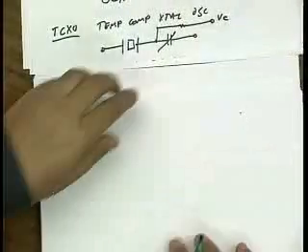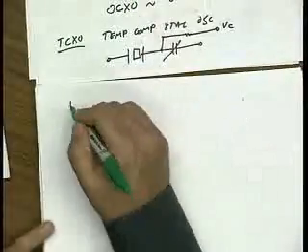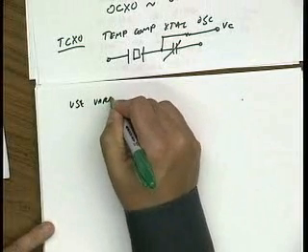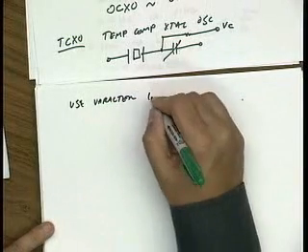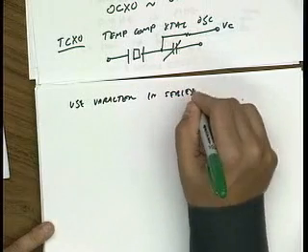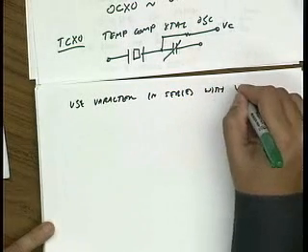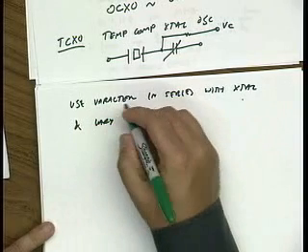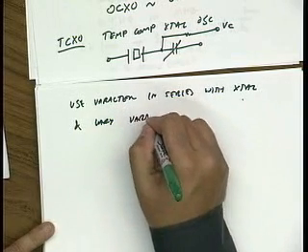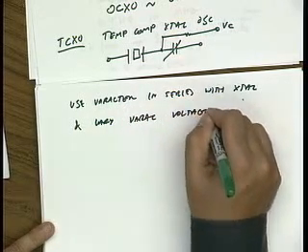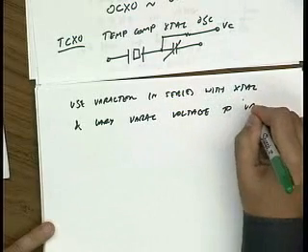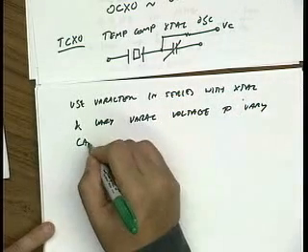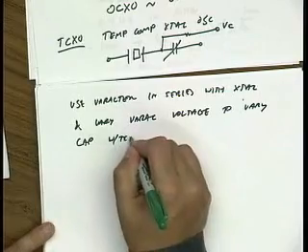Let's write a few words down. We're going to use a varactor in series, let's say, with a crystal, and vary the varactor voltage to vary the capacitance with temperature.